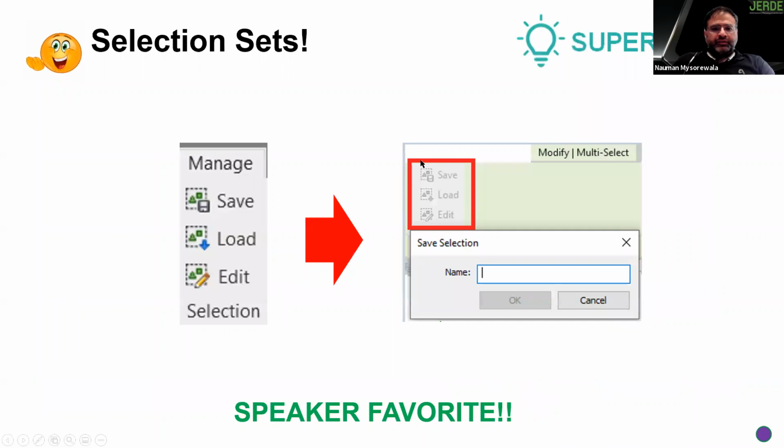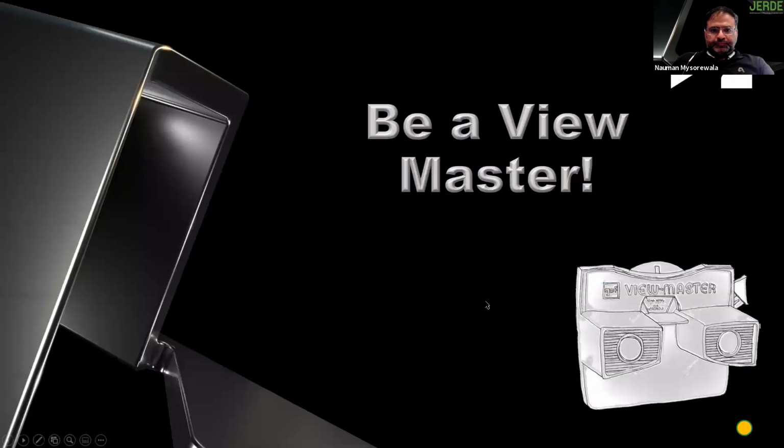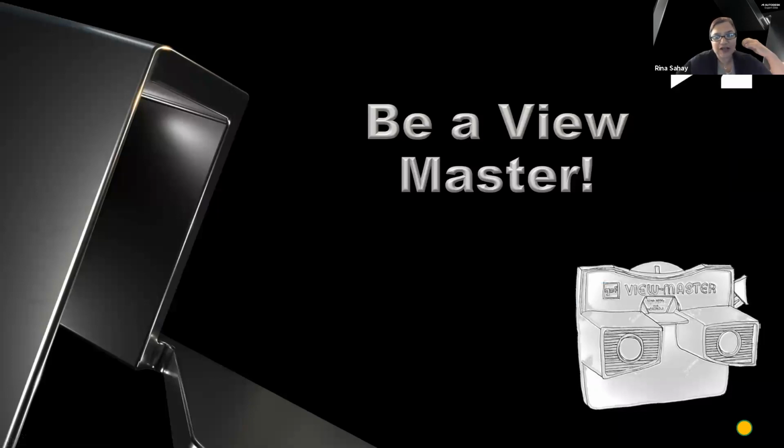Another favorite of mine is these selection sets, where you can save them, load them up, and edit what's in there. This is a static selection set, but you can update it and add more to it as well. The other nice thing is that for the elements that are part of that selection set, you can apply filters on them as well for visibility graphics override. So that's another benefit of this.